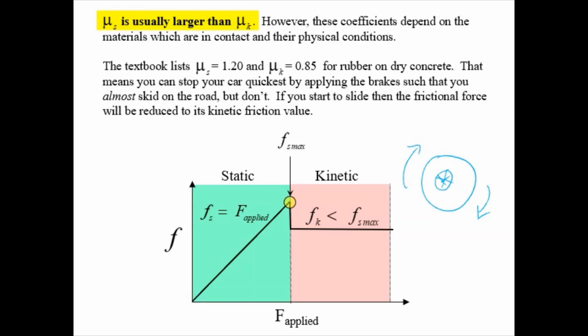So when you slam the brakes on in an emergency situation, or you just put the brakes on and don't know how hard to push on them, and you push as hard as you can, what'll happen is if the wheel stops turning, that is, if the wheel starts to skid on the road, that means you're over in here, and the sensor will feed back and tell the car's braking system to reduce the braking force. And then once the wheel starts to roll again, it will tell it, okay, now increase the braking force.